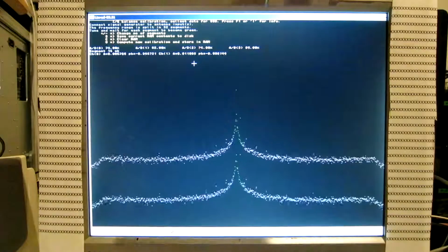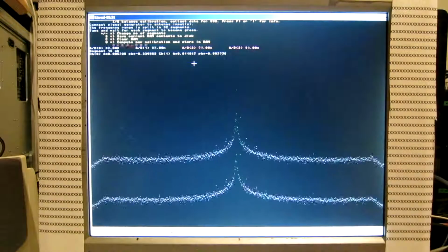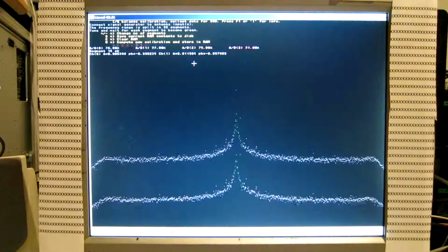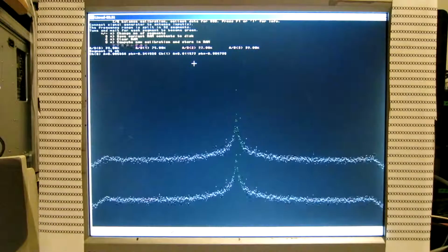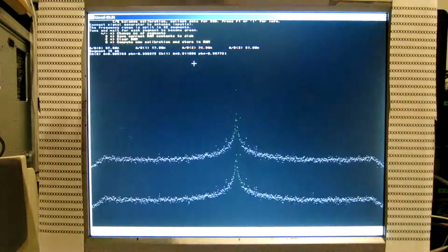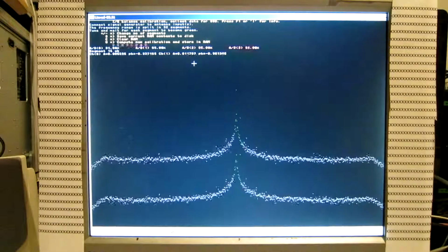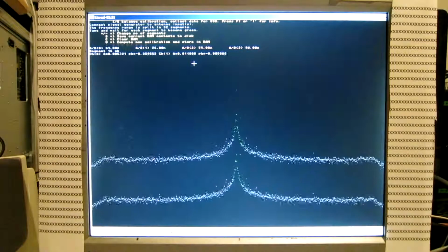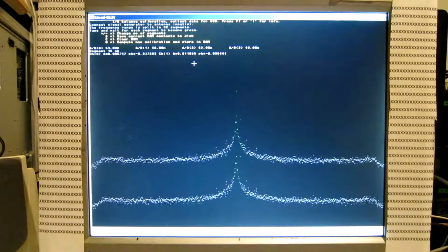The algorithm has to be able to separate this one from that one, which certainly wouldn't be any problem with these positions. But it's also good to have the signal not too far away from the center of one of the green regions. You can see overload is blinking here. This is minus 10 dBm. I changed to minus 13 dBm. Like that.